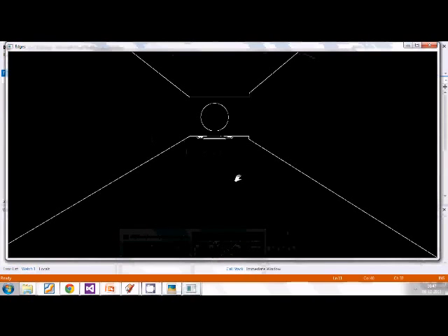And you can assume, of course, that you have two major lines here. Once you get the two major lines, you get their slopes, see their sum, and make your robot move accordingly. And the algorithm can be simple. It can be that as long as the sum of the slopes is almost zero, keep moving forward until you reach the end. That's a different state we'll come to in a minute.